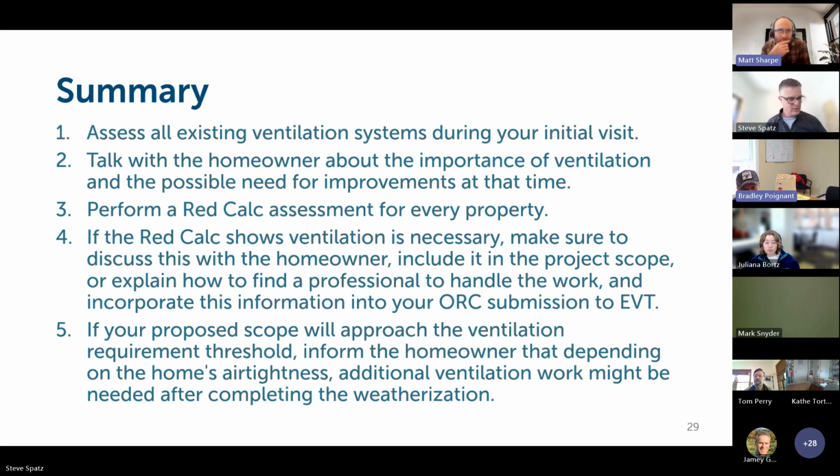When you do the calculation, when you measure, so basically, if the basement's finished and it's all below grade, it's not walkout, but it's completely finished with the TV, couch, would that be considered then? So the height of the building, which is part of the calculation, is from grade to the highest point of the thermal boundary. And the floor area is a completely different set of rules. Is it finished occupiable space? So in that scenario, the finished basement is, yes, part of the conditioned floor area, but the height of the building only starts at grade. Okay.